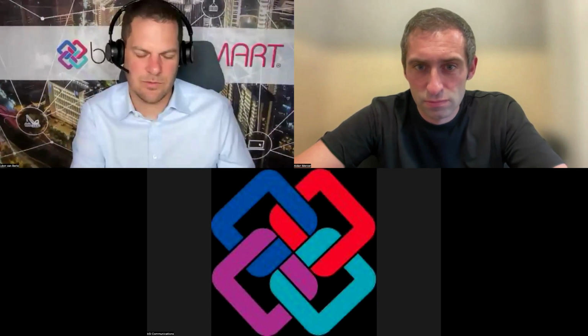the answer to that question lies, of course, with the client. If the client thinks it's really important that the information is being provided like that, then it is important. If it's less important and you just need to know some properties, then that's the case. So the only answer that I can give is that IDS does allow you with this part-of facet to make these requirements. We do not see that a lot in practice. So most use cases in practice are mainly requiring properties and classifications and some types. But if you really need a stair to be decomposed in a certain way, IDS allows you to require that.